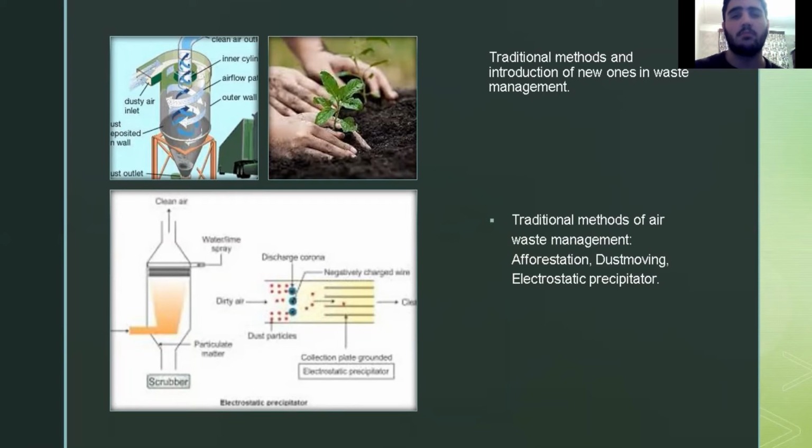Electrostatic precipitator method. The dust extraction device used to remove dust from the dusty gas is called an electrostatic precipitator. The separating force has a direct influence on the particle in the ESP process, and rather than the whole airflow, giving the particle separation process minimal energy consumption, low air resistance, and excellent dust removal efficiency. There are other methods like wet dusting, bag dust collector, inertial impact, diffusion effect that are commonly used in air pollution control process, and they are all traditional methods.